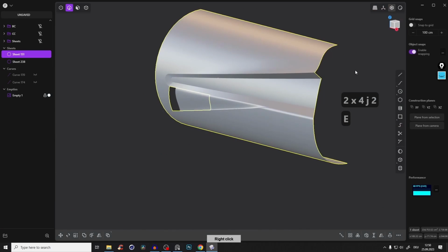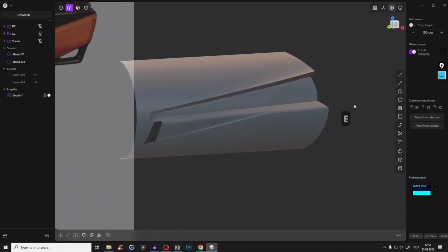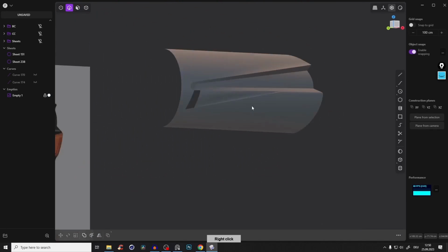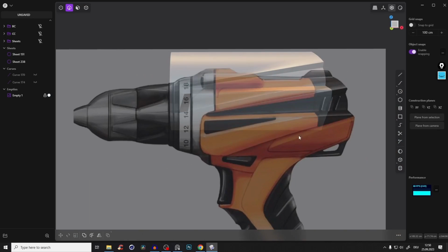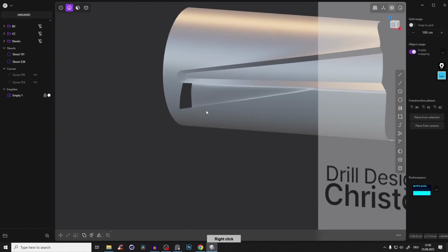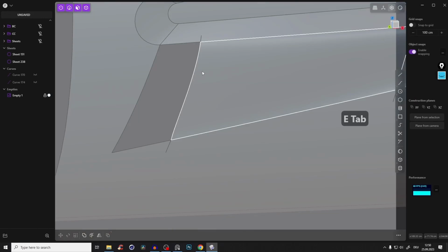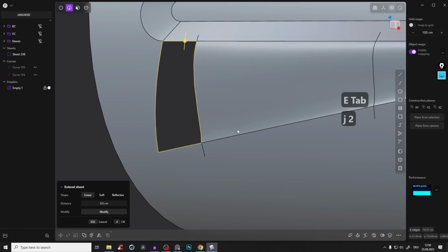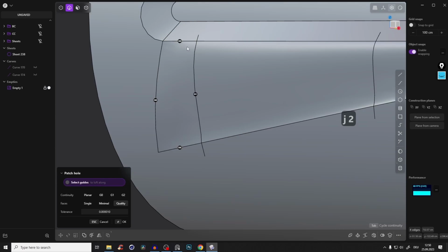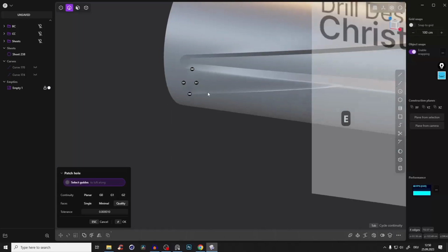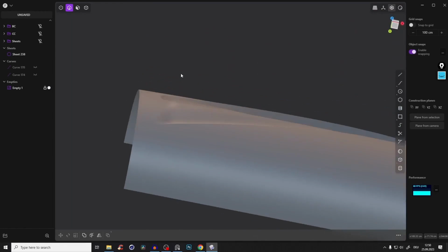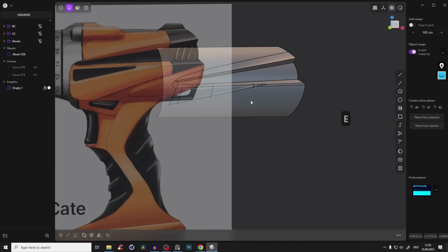And yeah, look guys, I really love this sharp edge and how it goes into the smoothness. So you see, we have a very similar result. And here again, select that, join, and here we have to patch this. Add here G1, G1 and G0, and that looks okay. Again, we would have to add a few more lines, but this is completely fine for now.